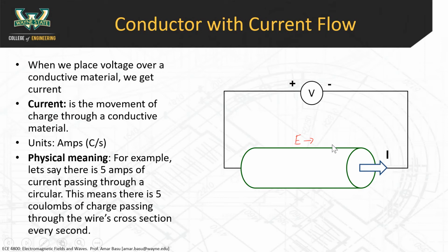All right. Just to clarify, so there's no confusion about this electric field issue: in a perfect conductor, the electric field is equal to 0. In a very good conductor, the electric field is near 0. And in a resistive type material, you can have an electric field like this. The current is defined as going from the positive voltage to the negative voltage. So this is the positive voltage on this side, and here's the negative voltage on this side, so your current flows from left to right.